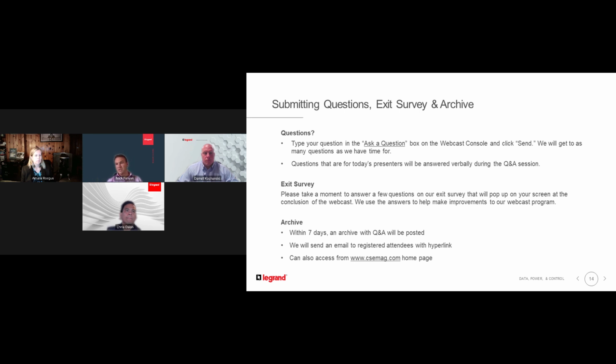Obviously, fuses are the same way. We do CCP fuses with an Eaton fuse disconnect that does have a handle switch on there as well. Same deal. You could flip that on and off from the floor. Obviously, if you want to replace the fuse, you've got to get up on a ladder to do that. But that is all okay with the NEC code. So if I did not answer that the way you wanted it, please resubmit it, and then we'll make sure we get you an answer. But that was my understanding of that question.